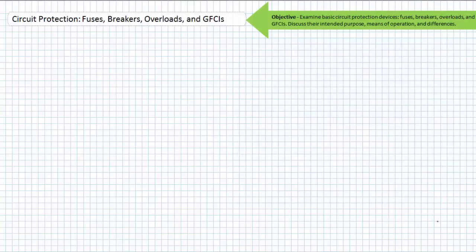If the fuse is suspect or cannot be visually inspected, as is often the case, one can step beyond the visual range and use an ohm meter to check continuity. An ideal fuse has 0 ohms of resistance, although real fuses will exhibit some tiny amount. A blown fuse should exhibit extremely high resistance.